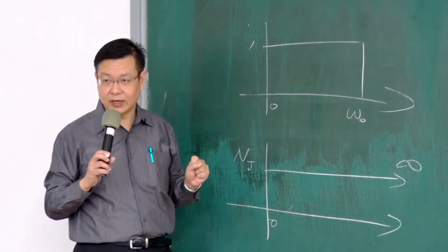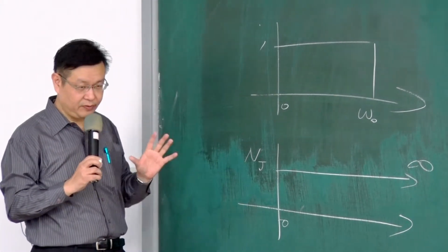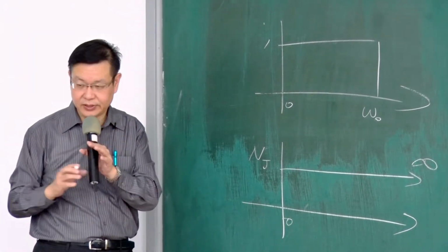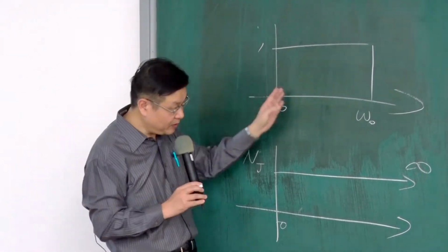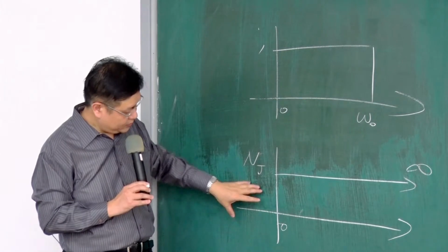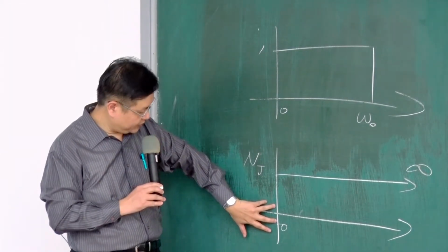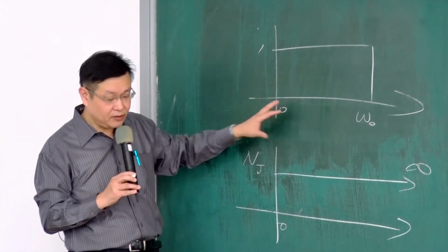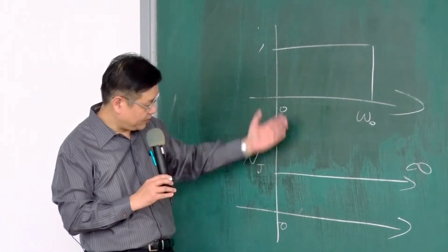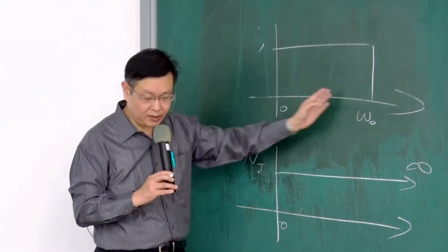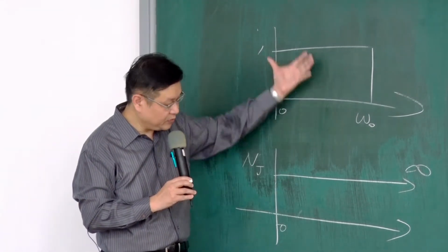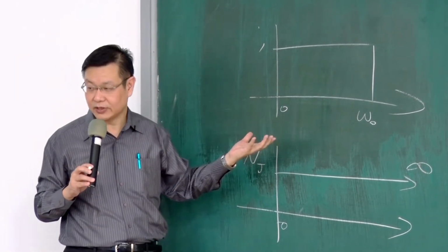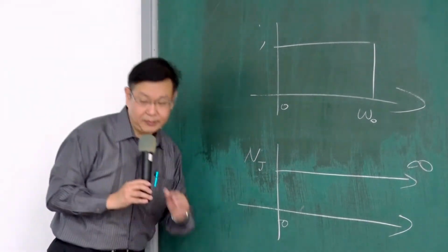So that's why sometimes, when we have a very high frequency response system, usually the system will become very noisy because you have a lot of noise coming through the window. You open a large window because Johnson noise is a white noise. So no matter from low frequency to high frequency, the noise level, the power, is the same. So the final noise power will be the integration of this product and also the window opened up. So you have a large open window, you accept more noise into the system, and you get a final integrated noise that will be much higher.